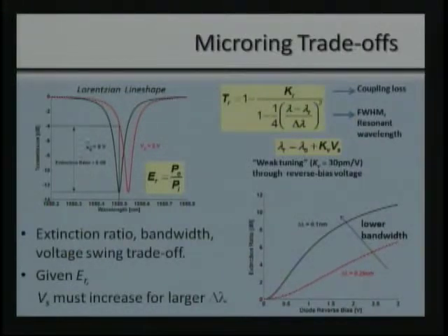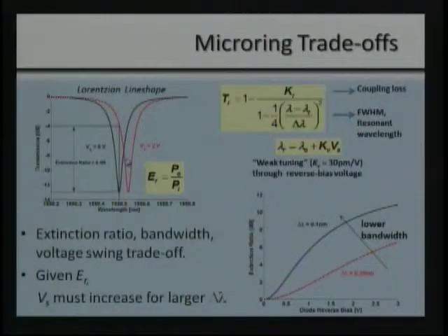So the reason that we get modulation is that our laser will come in at one frequency, at this 1550.5 nanometers, and when no voltage is applied on the ring, that laser light will all be absorbed into the ring. So that's like transmitting a 0 voltage level, right? Because all of the light's absorbed in the ring. But when we apply this voltage, just 2 volts, now suddenly that Lorentzian shifts, and the light will pass right past the ring. And that's like transmitting a 1.